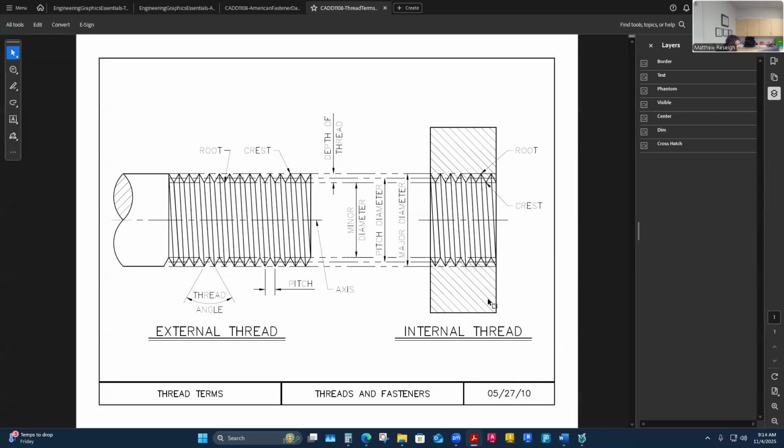So sometimes when maintenance gets done, those corners get cut, and we reuse fasteners over and over again, retorque them, retorque them, retorque them. Eventually you've actually ruined the fastener's potential to do what it's designed to do. So anyway, there's another tangent for you.